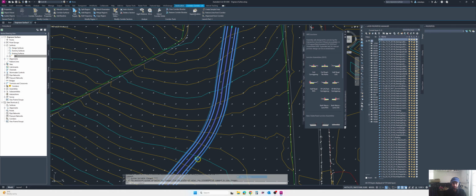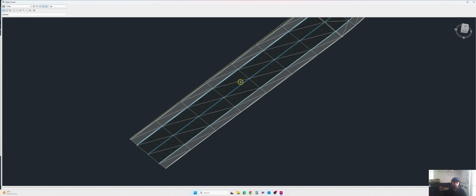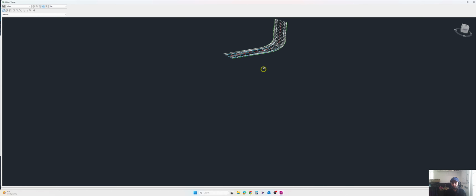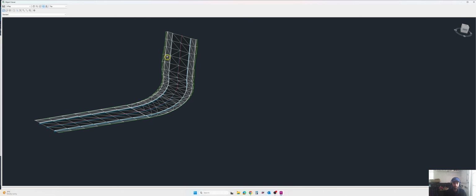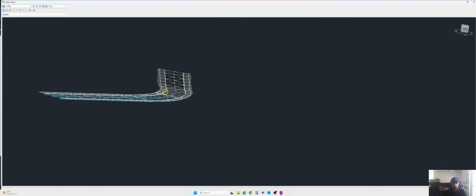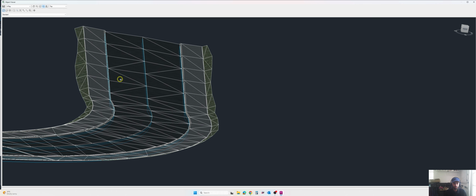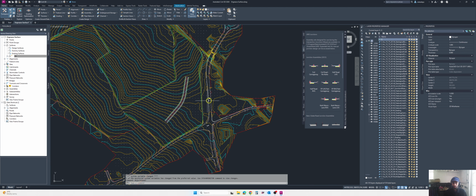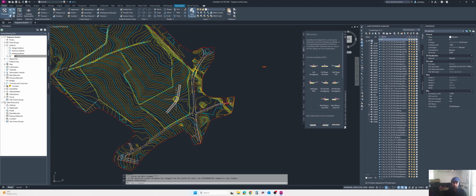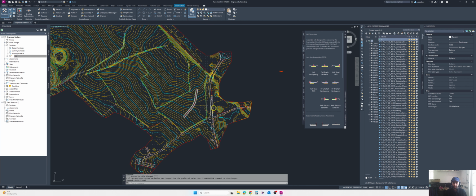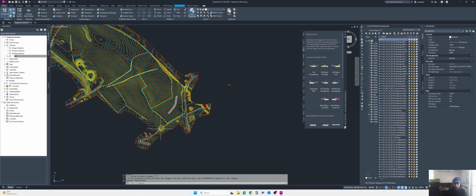And also in the object viewer, you can see now it's all fill. You can see the green line, it shows the fill, and then we have the curve, and you have seen the footpaths, and then the road. So this is how you can quickly use feature lines in order to create a small corridor, small bike tracks or anything. But for the main roads, I would suggest going for the alignment and profile. That's the main method to do it.